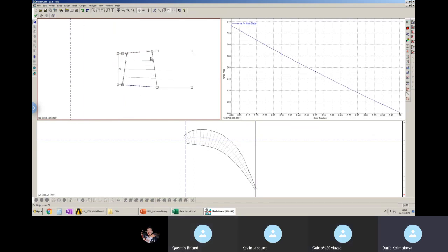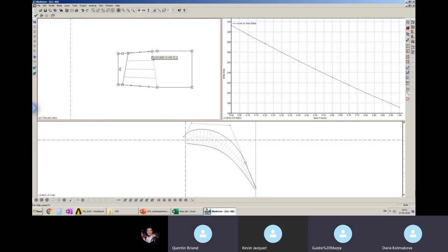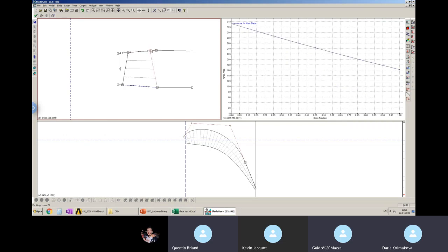If you cannot get the difference of 2 times between these areas, the second solution is to try to increase the area by changing the control points. But I think for my case, because the blade is quite small, I will leave it like this.